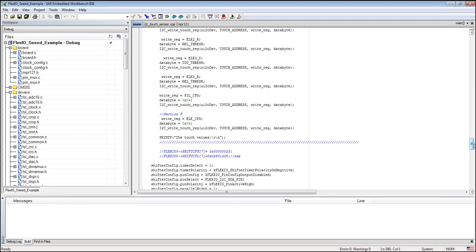Using some of the same strategies I overviewed today, by monitoring the I2C data and setting alarms and matches, you can not only know when any touchpad is being touched, but know only when all four are being touched, or two of the four, or three of the four, and also know that it's been touched a certain number of times. That's the example we're going to be posting that I was going to try and show today, but we're already at the hour.